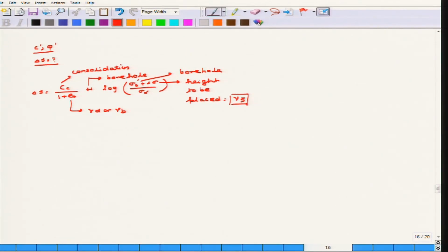Now, once you have obtained all these settlement calculations, you know what should be the settlement under that permissible load. Since I have considered a virgin clay layer here, delta S is only available for the virgin consolidation layer, and I have ignored the pre-consolidation part. One important aspect you have to remember here is that the clay layer may be of varying thickness, and I have also said that in case of varying thickness, you can use the effect of stress distribution to find out the effect of varying thickness.